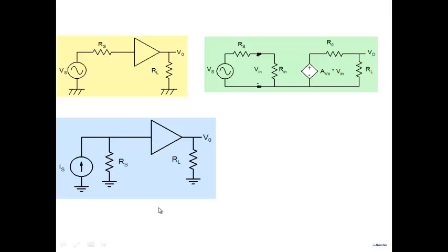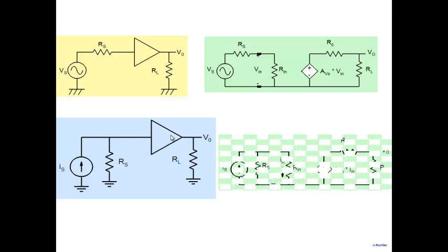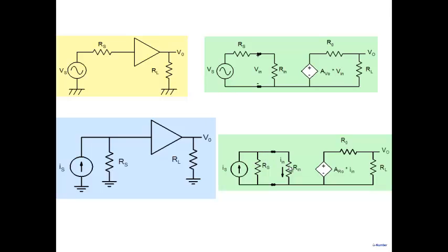You're looking for an amplifier. If this is a signal, IS, you want this entire signal to go into the amplifier, right? What kind of an input resistance do you want? Low input resistance here. You want everything to go into the amplifier. So here, you are interested in input resistance, which is very low. Is it pointing towards something? That common base amplifier with very low input impedance is ideally suited for current source input, not for a voltage source input.